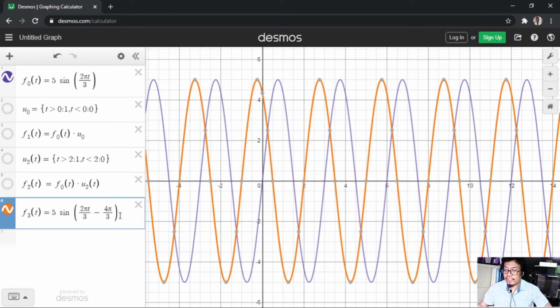This delayed signal, as you can see, has a 0 value at 2 seconds. So essentially, this is what we now consider a signal that is delayed by 2 seconds, because instead of starting 0 at 0, it actually started with another value at 0. In the original signal, this value would not be encountered until 2 seconds after.